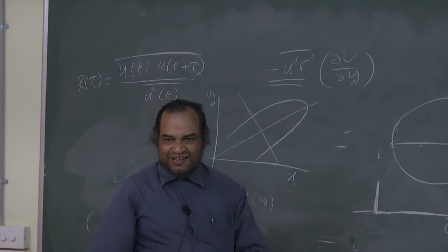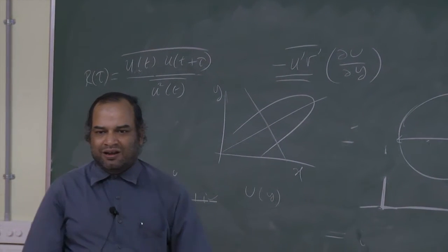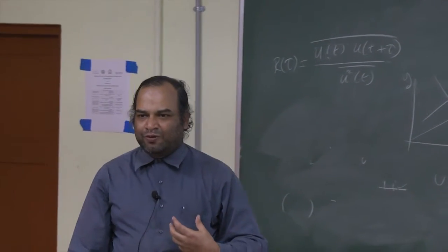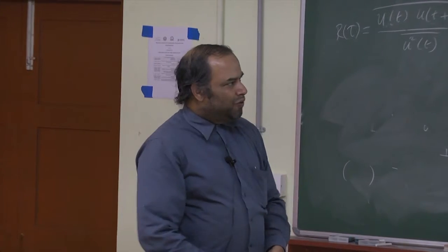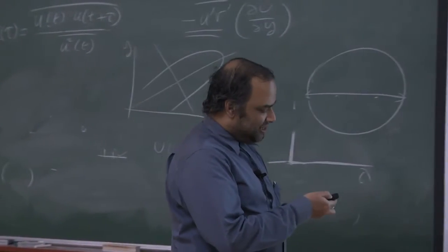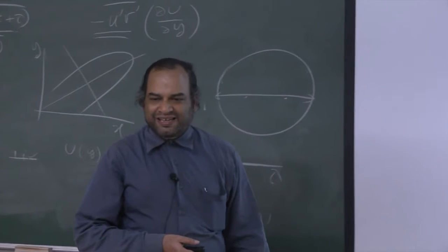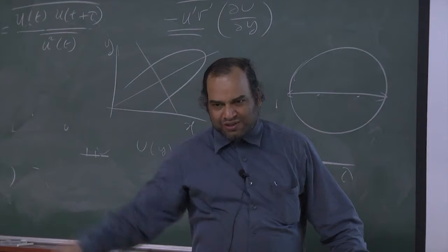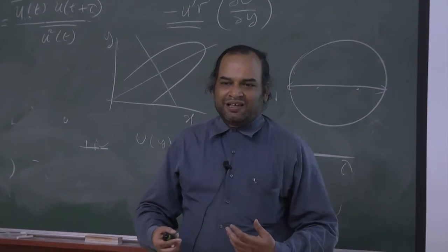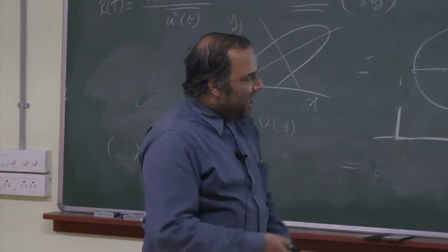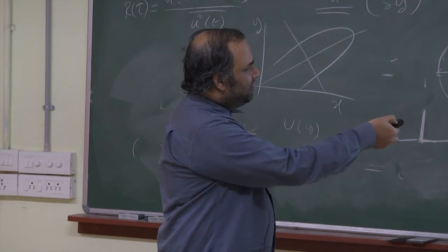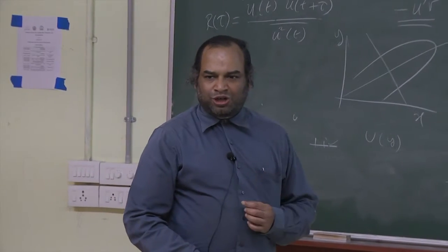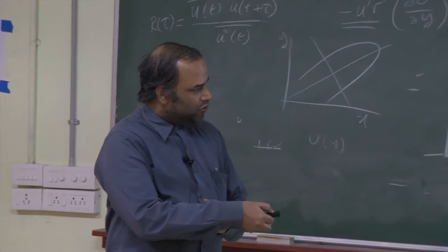And it passes on that energy to smaller and smaller eddies. So the larger eddy is one which gains this energy from the mean flow and passes it on to smaller scales. Now what's interesting is that the larger eddies have relatively longer time scale, because they are long; for it to even do a circulatory activity, crudely speaking, would take longer time. As the length scale becomes smaller progressively, as you go down this, the time scales and length scales all become shorter till you reach what is known as the Kolmogorov scale somewhere here.